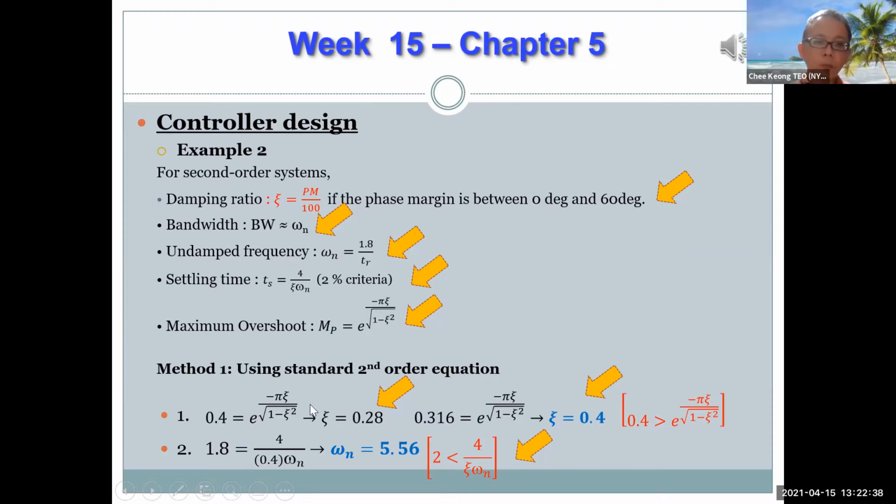But with just now the previous two specifications, the peak overshoot is given by this formula and is less than 0.4, right? If we use exactly 0.4, then we are just designing exactly at the borderline. What if the calculation is not accurate? It might fall outside or fall inside. So depending on the choice, a trial calculation of what is zeta, if we put 0.4, we get zeta about 0.28.